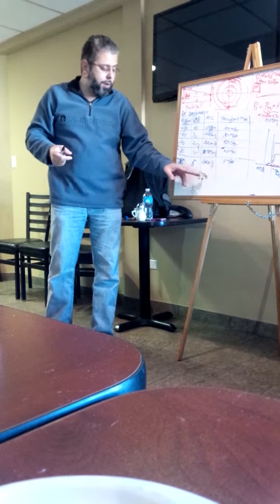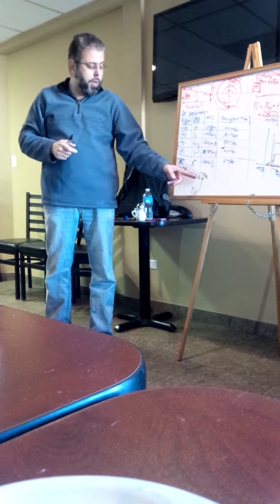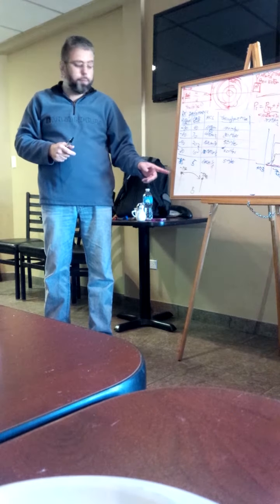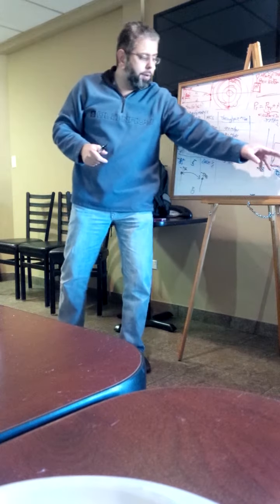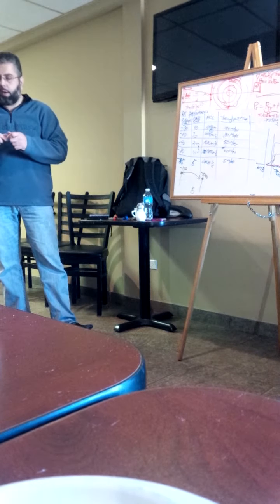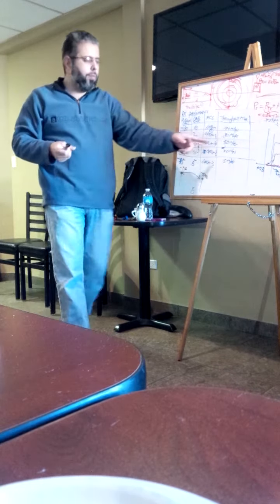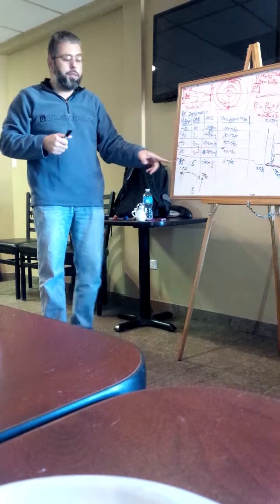So turn the power off on both of these, turn the transmitters off, and put them into listen mode, spectrum analysis mode, and you can hear what's going on. You should be able to see immediately that there's something causing you interference at about -70. You'll say, okay, I understand. If it's only giving me this much throughput, I know why. There's got to be interference somewhere in the -70 dBm range. There's got to be somebody there, and when you turn on your spectrum analyzer, you'll see them exactly.